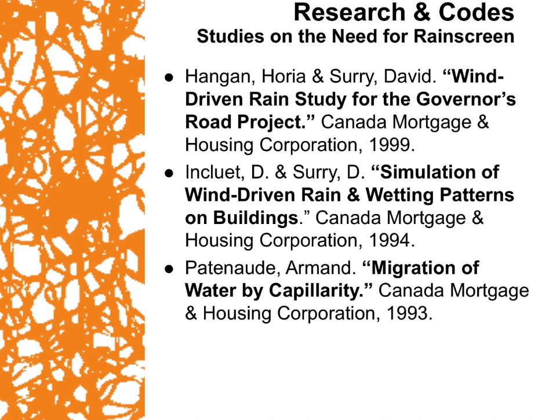The main conclusion from both of these is that the more moisture that you get on your facade, the higher chance or probability you have of having a moisture problem. It's a pretty simple concept. More moisture equals more problems. One of the good things that came out of this study is they realized a one-story building with an overhang of at least 1 foot has in the low teens chance of having an actual moisture problem, whereas a one-story building with no overhang has a higher chance, in the mid 80s, of actually having a moisture problem.